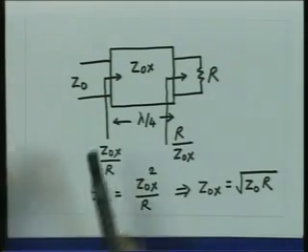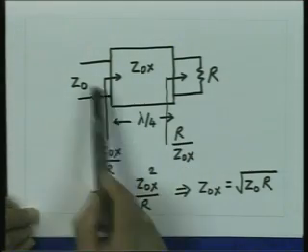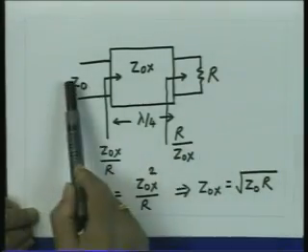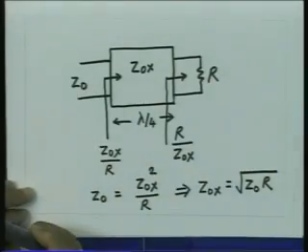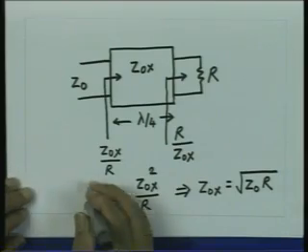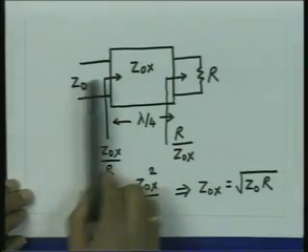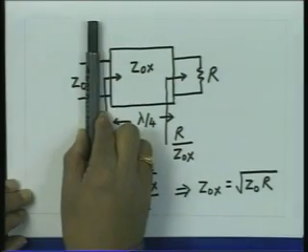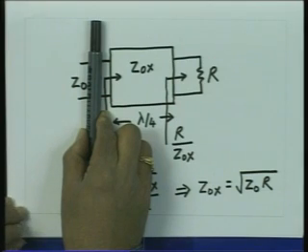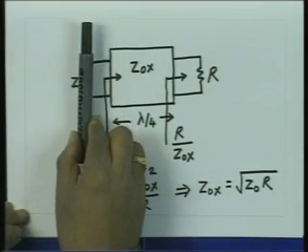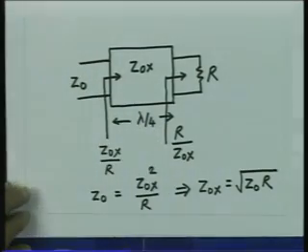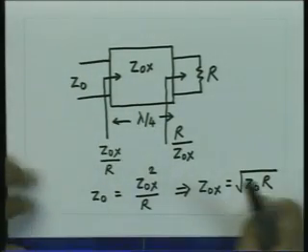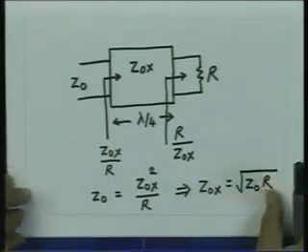and since we are introducing this section of a transmission line which is completely lossless, there is now a complete power transfer from the transmission line to the resistance R. So, without losing any power now, we achieved the impedance seen on the left of this box equal to characteristic impedance. And as we know, once the impedance becomes equal to characteristic impedance, every point on the left of this line will always be equal to characteristic impedance. So, this technique is what is called the quarter wavelength transformer technique.